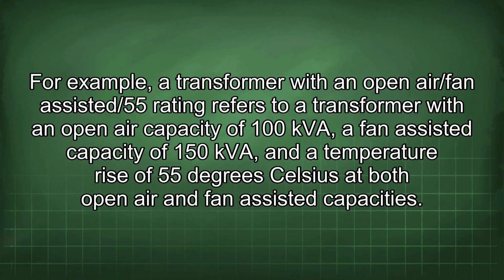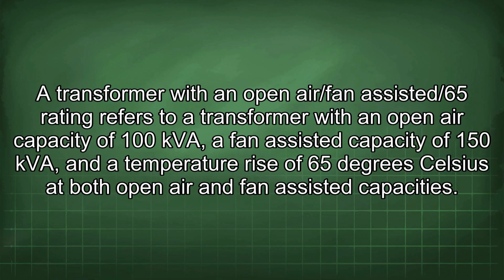open-air/fan-assisted/55 rating refers to a transformer with an open-air capacity of 100 kVA, a fan-assisted capacity of 150 kVA, and a temperature rise of 55 degrees Celsius at both open-air and fan-assisted capacities. A transformer with an open-air/fan-assisted/65 rating refers to a transformer with an open-air capacity of 100 kVA, a fan-assisted capacity of 150 kVA, and a temperature rise of 65 degrees Celsius at both open-air and fan-assisted capacities.